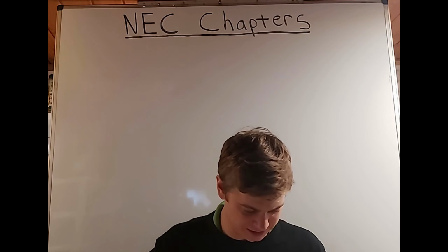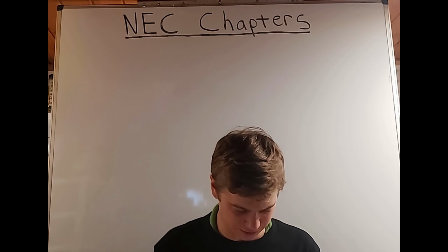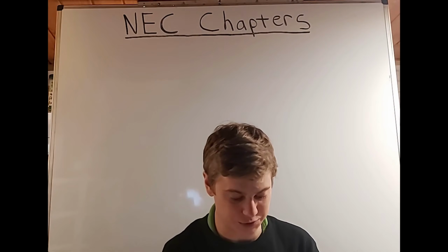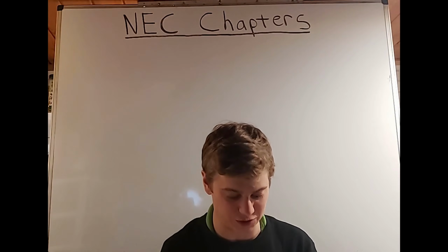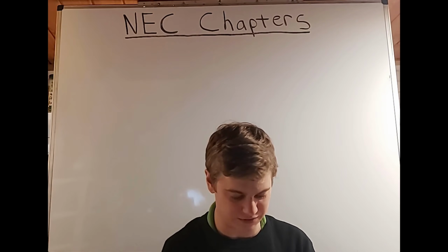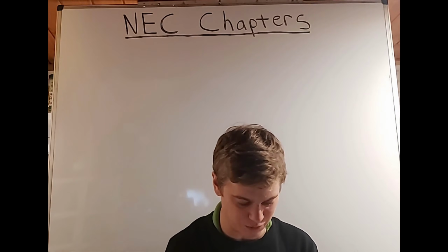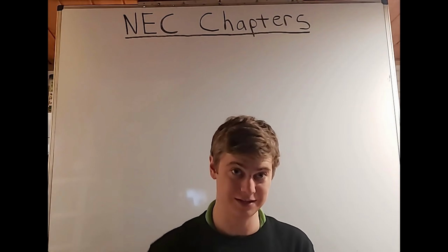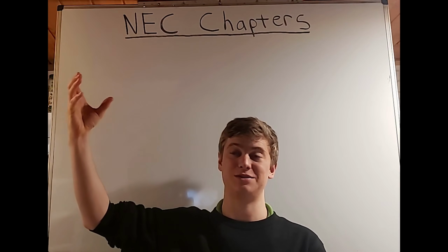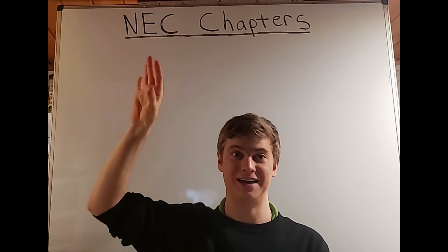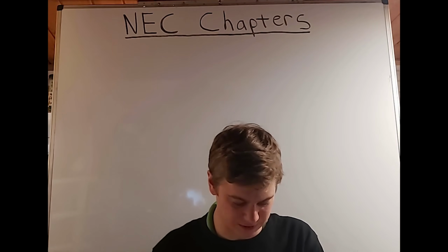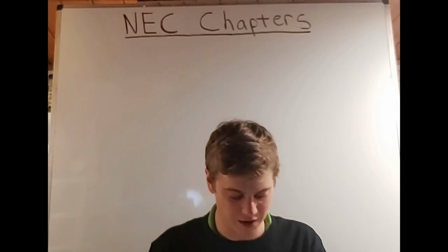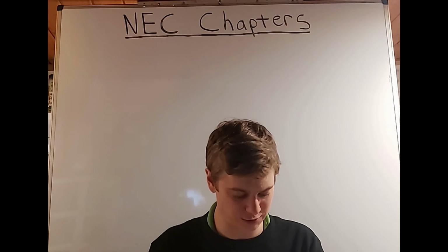Okay, and I'm mentioning this because you have exception 1 and exception 2. Exception 1 says that a receptacle installed solely for the electrical supply and support of an electrical clock in any of the rooms specified in 210.52(B)(1) is allowed. That is your exception, and that is off your small appliance branch circuit. Okay, so you can have a dedicated outlet that's used for powering and supporting a clock. And then exception 2 is receptacles that are installed to provide power for supplemental equipment and lighting on gas-fired ranges, ovens, or counter-mounted cooking units.